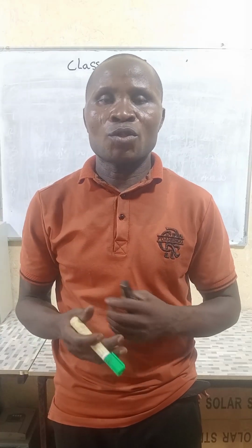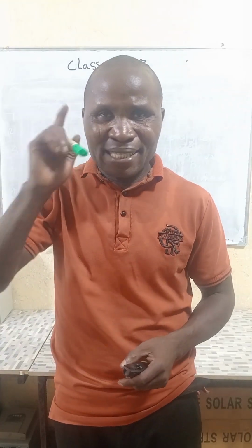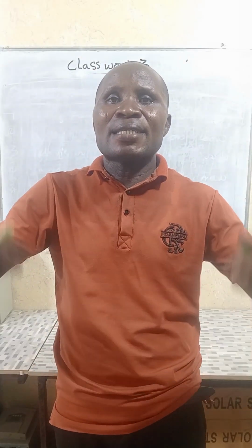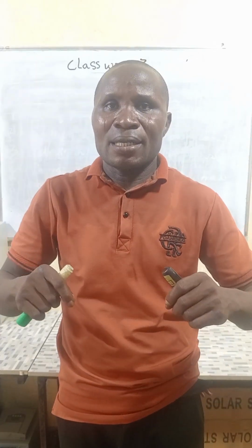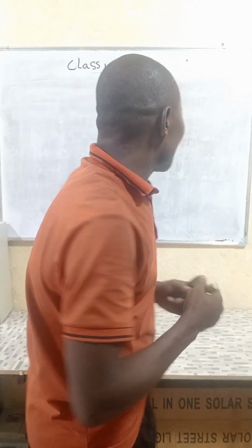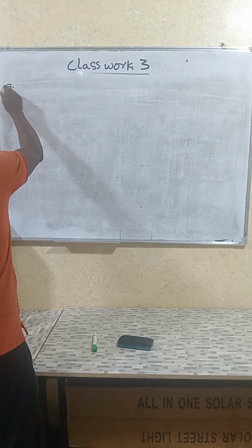So we are looking at the total given load, which is what? 3000. Now the running hour per day is 10 hours. How do you calculate the battery capacity? The battery capacity is the total load times the running hours per day. That is going to be your battery capacity. Battery capacity, that is A.